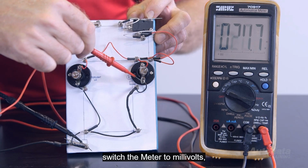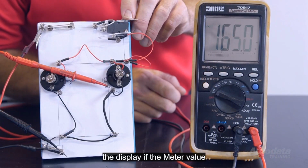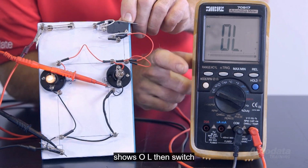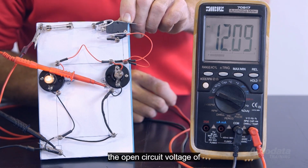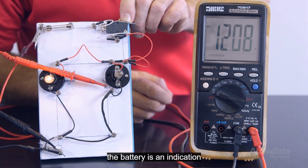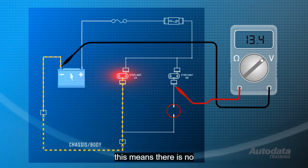Switch the meter to millivolts, operate the circuit, and read the display. If the meter value shows OL, then switch the meter to volts DC. A reading equal to the open circuit voltage of the battery is an indication of an open ground path. Again, this means there is no current flowing in the circuit.